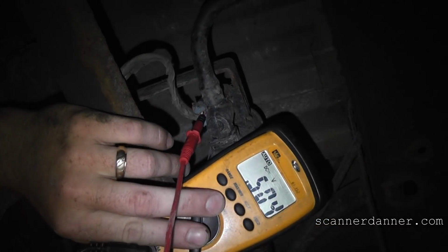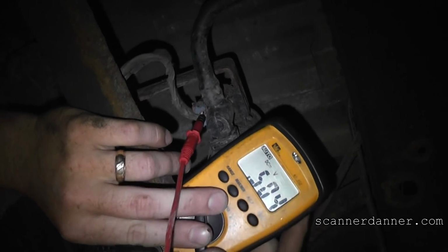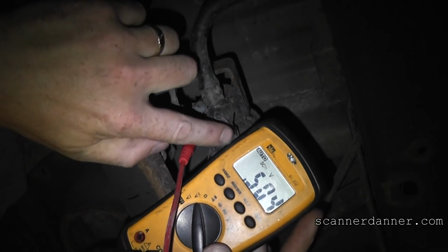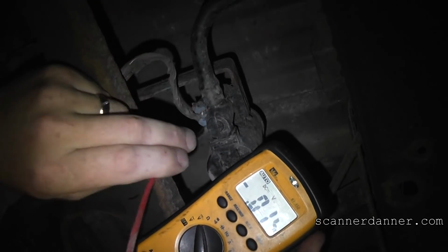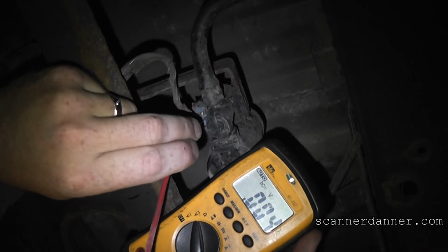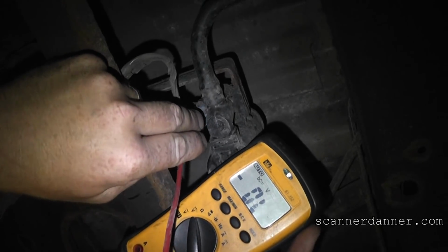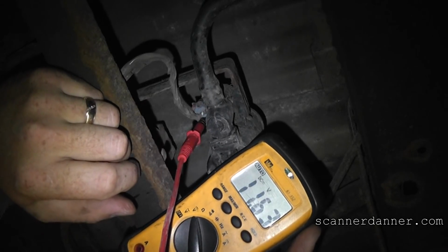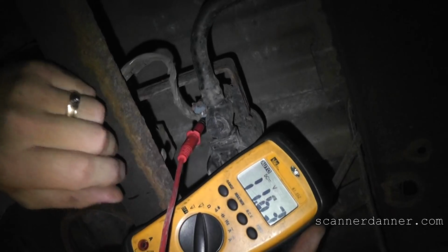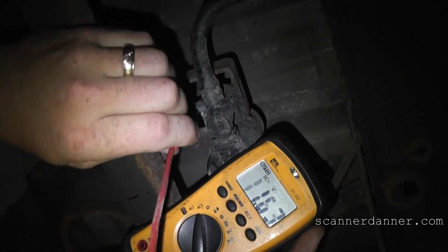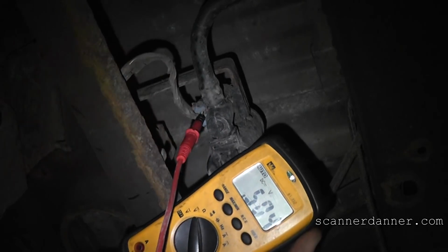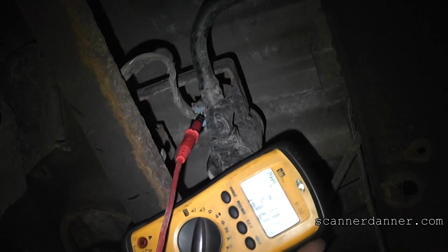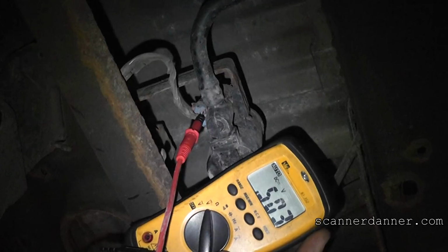So what that tells me is either I have a bad ground again on my meter, so I should probably bounce back over and double check my power feed. Let's do that. Make sure that my meter reads 12. 11.6. So how's my ground on my meter? Good. Come back over here. Measure this. I'm reading 500 millivolts, guys. 0.5. You see it? 0.5 of a volt.